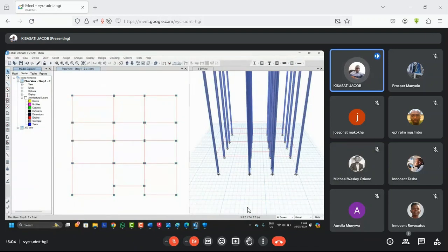These tools, as you can see them here. We have this tool, the one telling you to draw the beam. Just click on it, this one. Immediately you click on it, you will see this one up. Now the properties of what you want to do will come. Of course it's a frame. Then the beam property will pop up. So don't close this one. Instead of drawing, because this one is the manual drawing, come here, right click, then add the beam object.